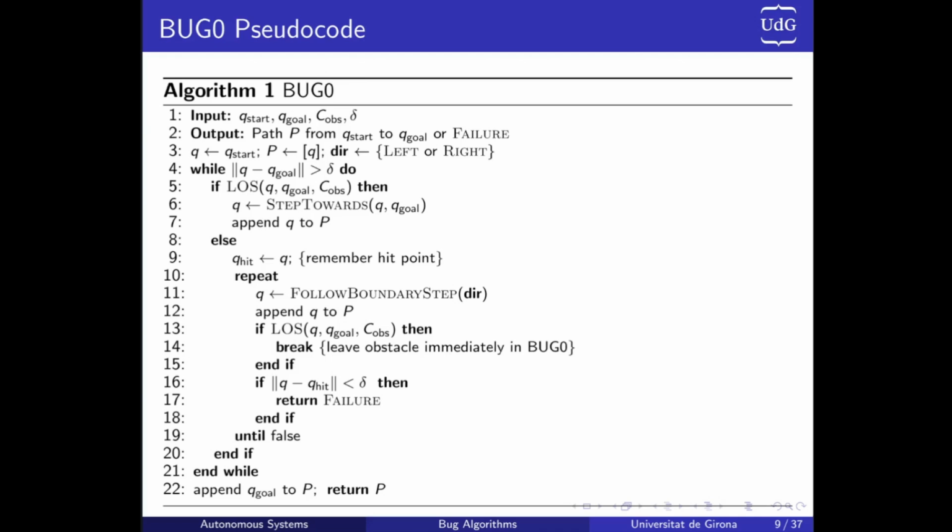However, we know that our robot, if it's a 2D robot, may or may not have an orientation. If we imagine that we have just a dot robot that is a point, there is no orientation, and then both Q start and Q goal are exactly the same, XY. However, if we think of a TurtleBot-like robot or a Roomba-like robot, then we need to somehow manage also the orientation of the robot.